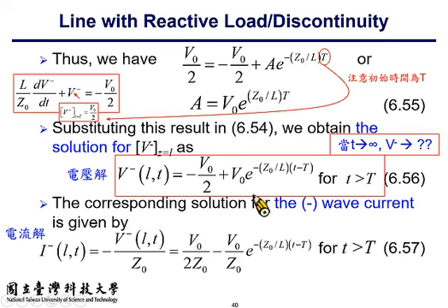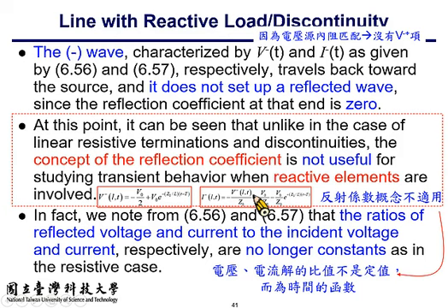So again, it confirms that for an inductor, when the inductor is charged up, its condition becomes approximately a short circuit. We found that the V minus voltage over V plus voltage also approaches minus 1, which again confirms the condition of a short circuit.